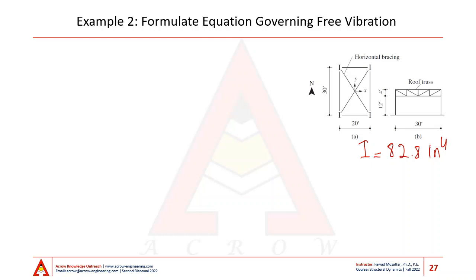Since it was specified that the trusses are horizontally braced at the bottom level, that means that the columns are going to be bent in double curvature, and there's going to be no rotation at the bottom level of the trusses, as indicated in section elevation B shown above. So the height of the columns that is going to contribute towards lateral stiffness is 12 feet.